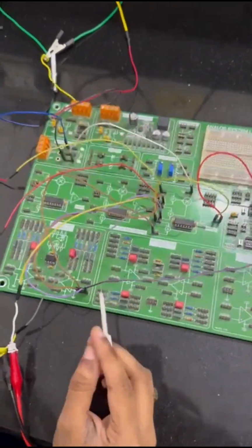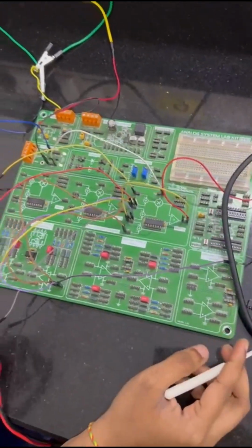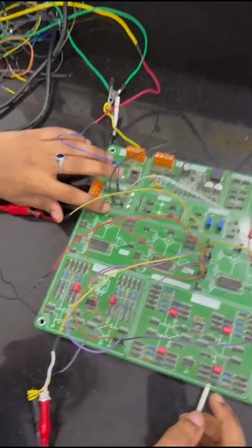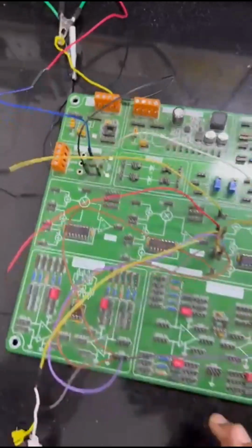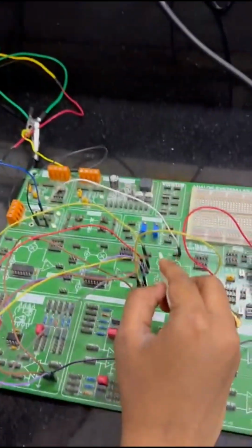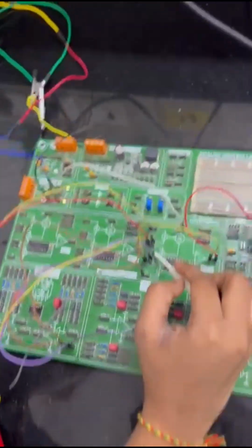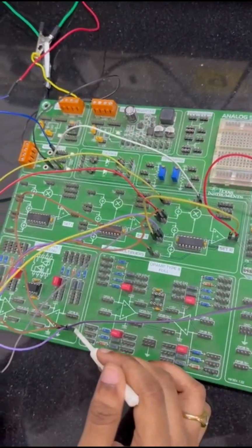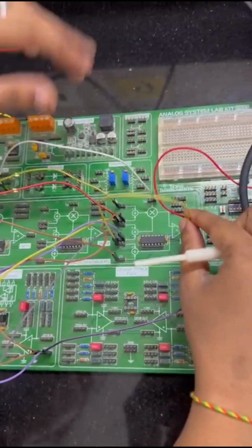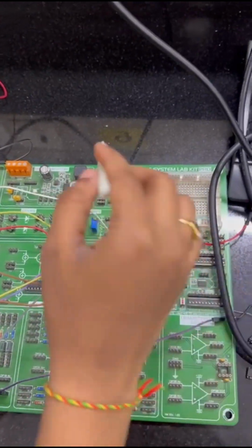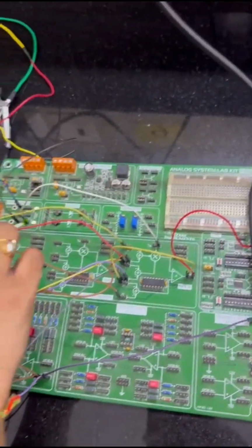Given that analog multiplier to multiply two sinusoidal signals. First, the power supply is connected here, as you can see, for the minus 10 volt, plus 10 volt, and then we connected the inputs. The first input is connected to X1 here, and the second input is given to Y1. And then X2, Y2, and Z2 are connected to ground, and then this output wire is connected here, and then we connected the 1 by SF to minus 10 volt.